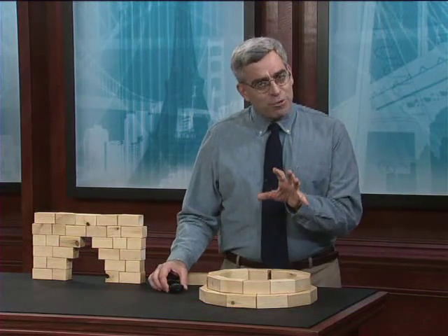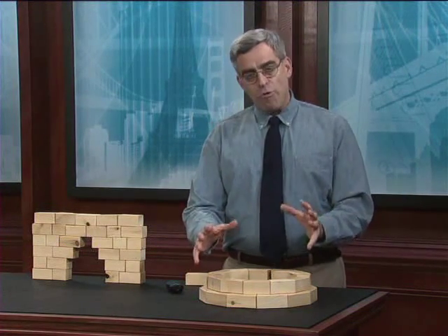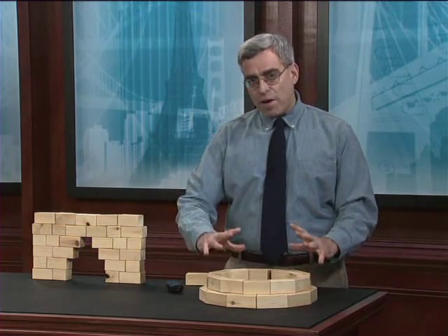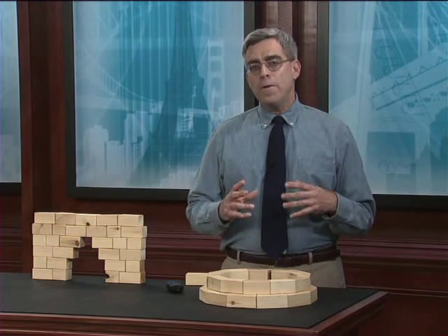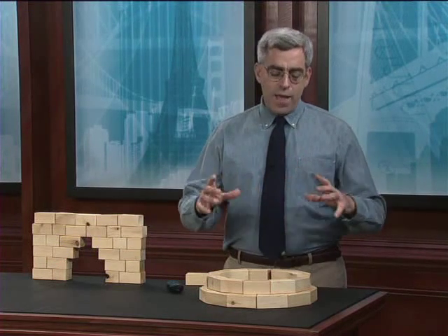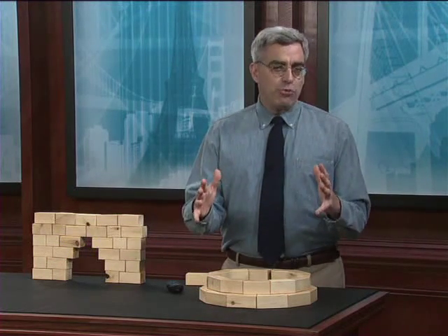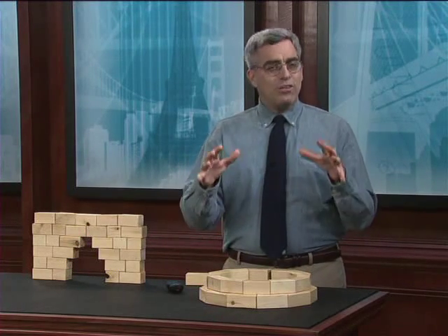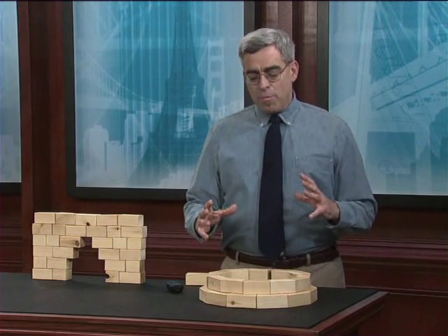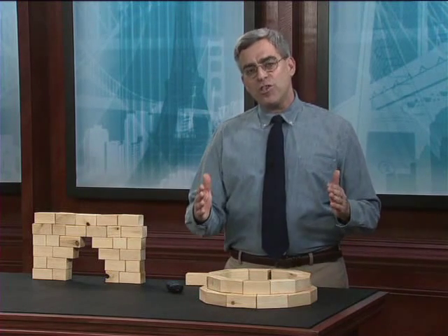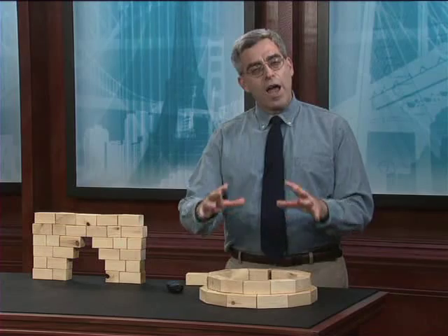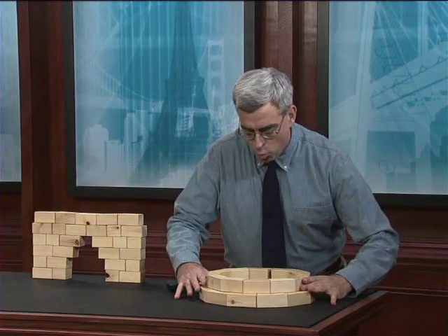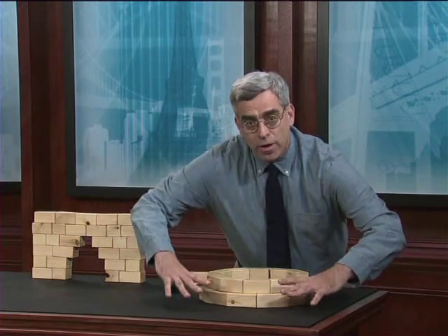But the defining characteristic of the dome is the fact that these overhanging stones tend to tip inward if they're simply left in this current condition. And that's the reason why the Treasury of Atreus and all of the corbelled domes that were built in Mycenae were actually built underground, because the only way to stabilize those successive layers of masonry as we get higher and higher on the dome is to provide some means of pushing that ring of stones inward.